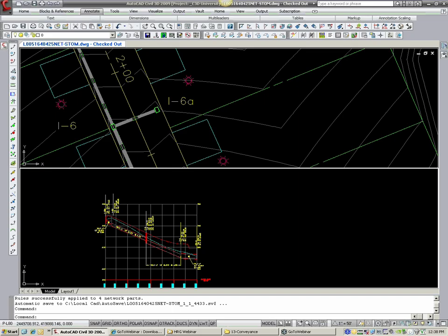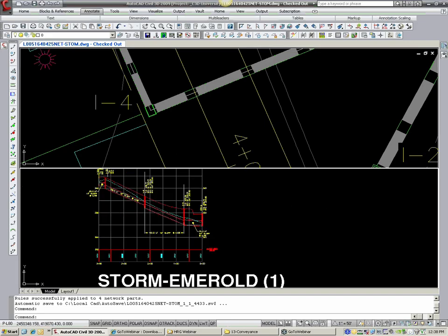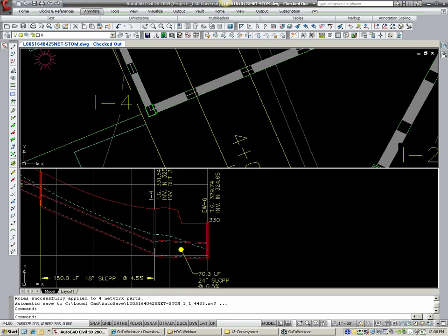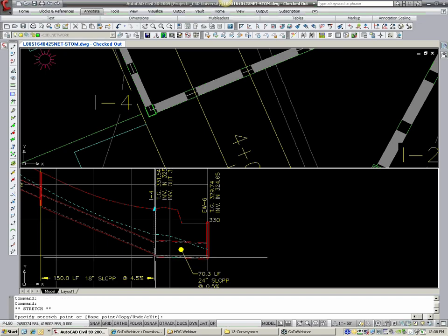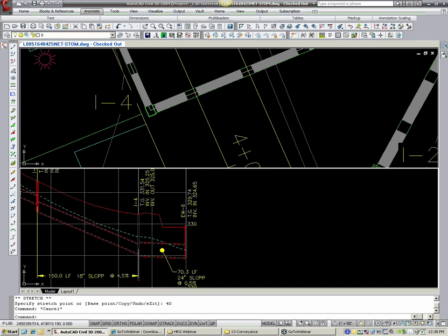Can you set a specific structure to have a sump? Of course. So say, for example, I4, and I wanted that I4 to have a sump. Maybe I have a snout in there. Well, I can do a couple things. Chris's question was, can I have a structure with a set sump? Sure. I want to take this structure, and maybe I want to graphically just come down, I don't know, 4 feet. So I type in 40 because it's profile and extrusion, so on and so forth, and hit enter. And now that inlet has a sump.